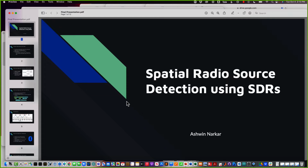Okay, so again, I think there's a lot of cool stuff that can be done, and particularly SDRs, like I said, there are sub $100 SDRs which cover a lot of interesting bands. Okay, as long as the project doesn't involve transmission outside what are called ISM bands. ISM bands are the bands in which your Wi-Fi operates, or some of these devices. There you can transmit relatively freely, but elsewhere you can't. So for projects like these, you have to make sure that you're using the right bands, but it's a very interesting space to work in.